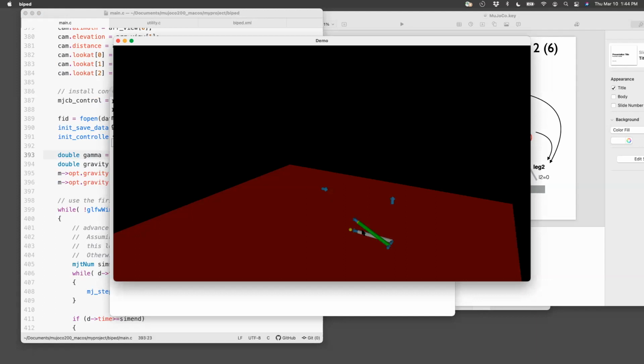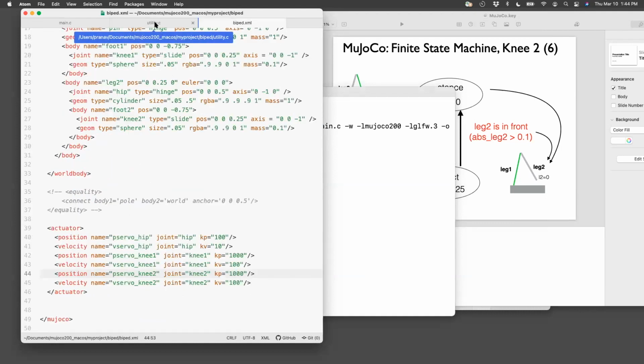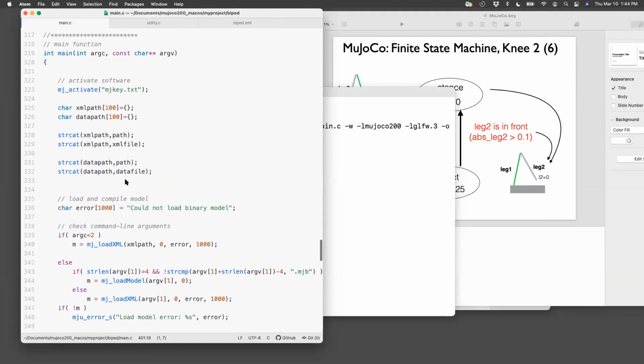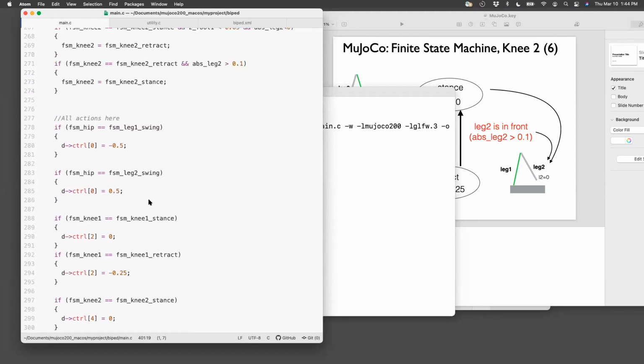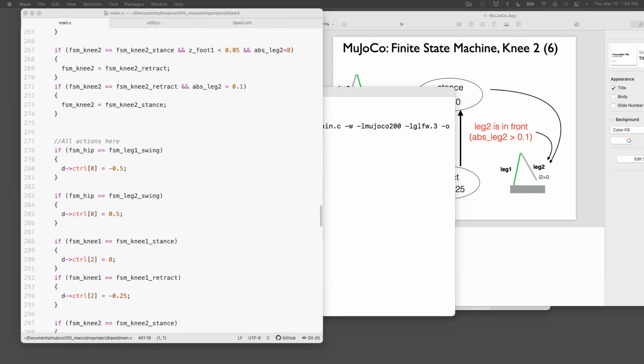So there is a problem with the leg not swinging in front. That's clearly the problem. It went forward. Now the green leg, or the leg 1, didn't swing in front. So we need to figure out why that's happening. Okay, so it's probably here. Either the FSM didn't transition or it is something else. Okay, I'm just trying to think what could be there. We could, well, this is right. Okay, 0. That's right.